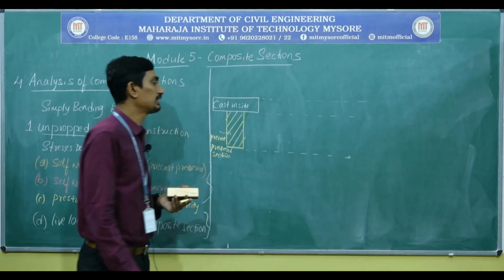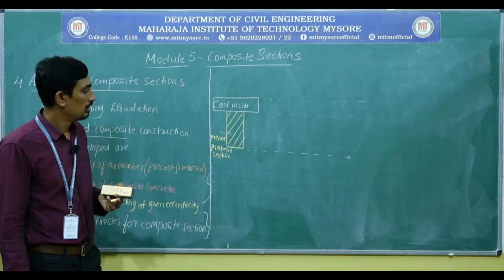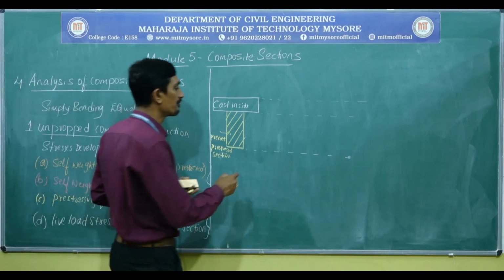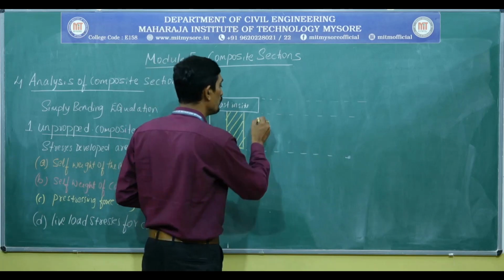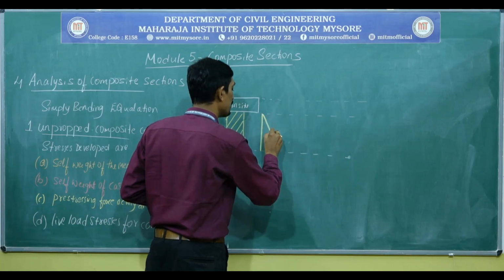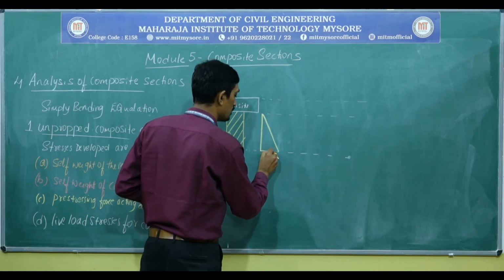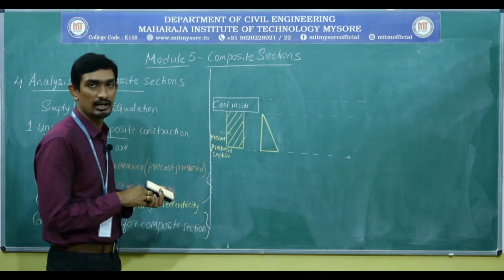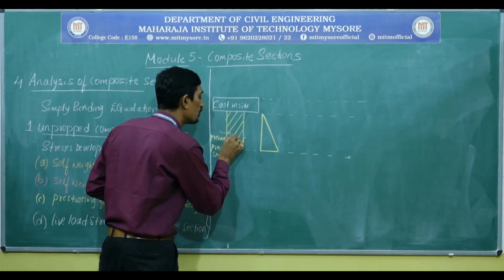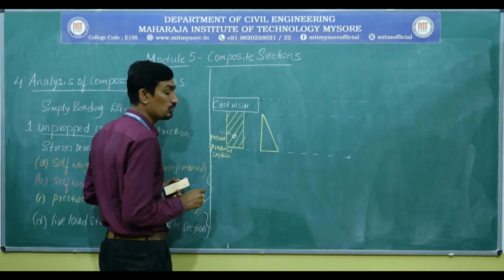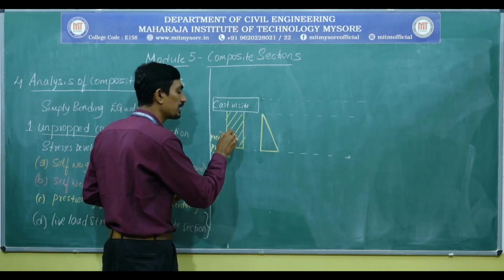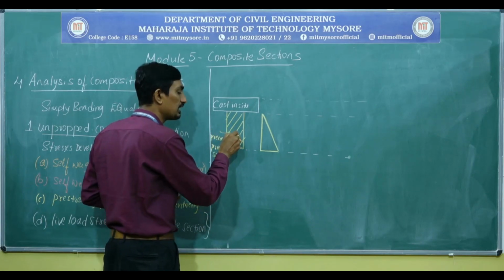So now as I stated, the first thing, the stresses encountered will be due to the pre-stressing force induced. I am going to induce the cable at a particular distance, so I am going to induce the pre-stressing force at this particular distance.